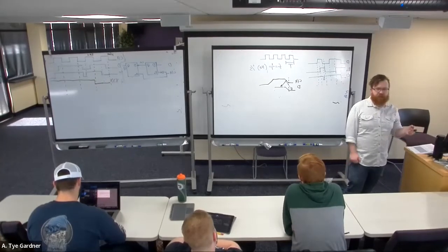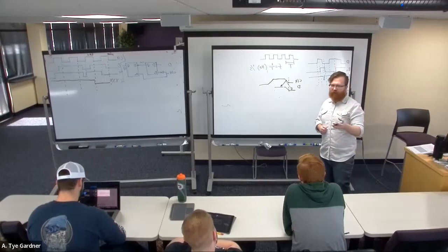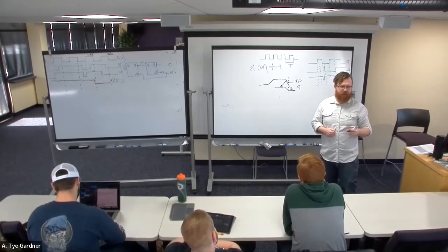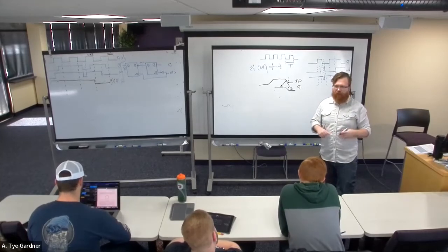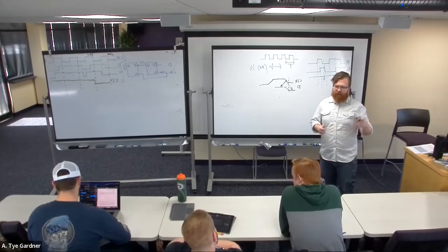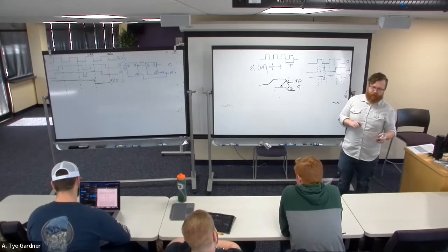So we need to set up the signal and hold the signal for a specific amount of time. And it's just in your data sheet. If you were to pull up the data sheets that you use to figure out what pins are connected where to the logic devices that you've built on breadboards, guess what? They're going to have a setup and hold time. And if you violate that kind of thing, then you're going to have weird abnormal behavior.